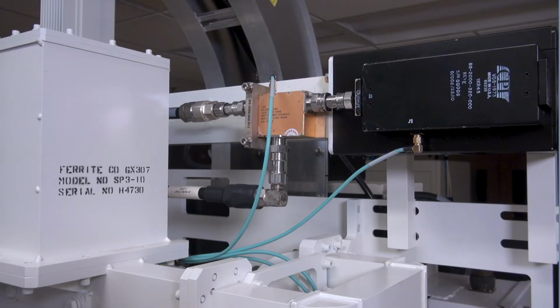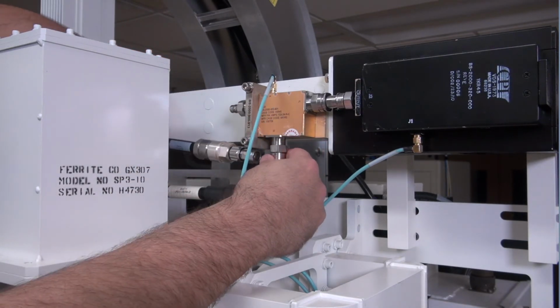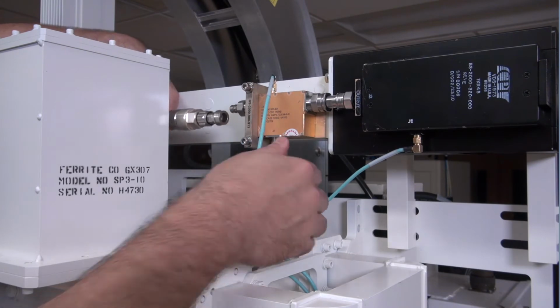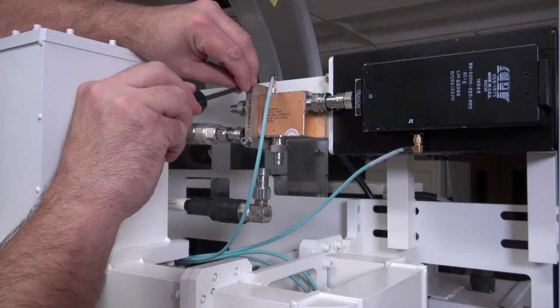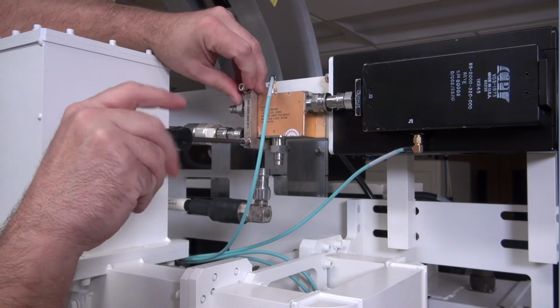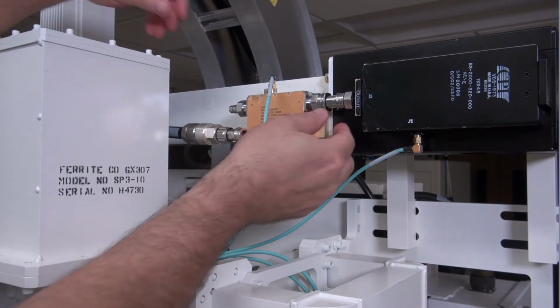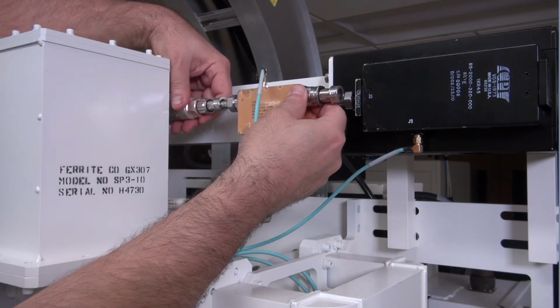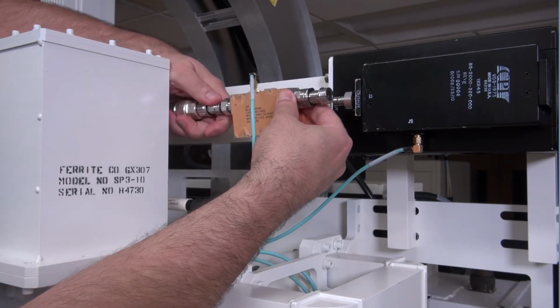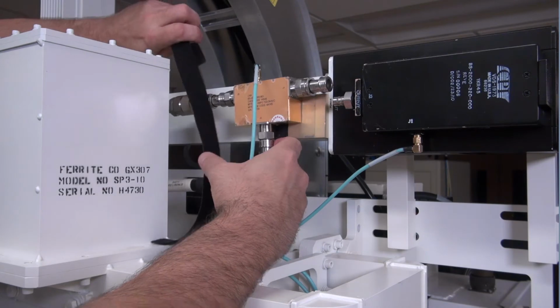Disconnect the horizontal LNA. The sequence of the following procedures reduces the risk of damaging the LNA. Disconnect cable 2W556 from LNA 2A5A4J3. Disconnect cable 2W577 from LNA 2A5A4J2. Remove the 3/16 Allen bolts and clamp from the LNA bracket. Disconnect LNA 2A5A4J1 from TR limiter 2A5A1J2. Reconnect cables 2W556 and 2W577 to the LNA.